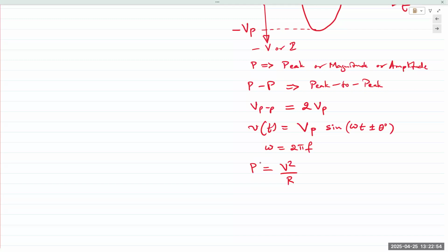You have a resistor R. If you connect resistor R to a DC supply, it will receive some energy. If you connect an AC, it will still receive some energy. So the value of the AC waveform that delivers the same energy, the same power in that resistor as the DC value, is the RMS value of the waveform. Obviously, we cannot take the average directly.